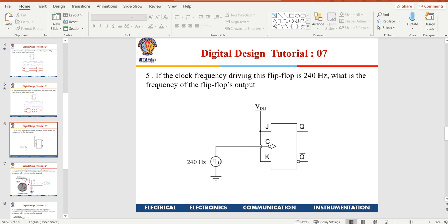When the next clock comes, our Q will get flipped to 1. It is toggle. Whereas Q bar was initially at 1, so it will continue to remain 1. You will not take that next state to feed it to D. So when Q toggles, won't Q bar also toggle? Q bar will toggle, but even before toggling, the input will be fed with the previous state. There will be a certain propagation delay here, so it will be first fed and then toggled.